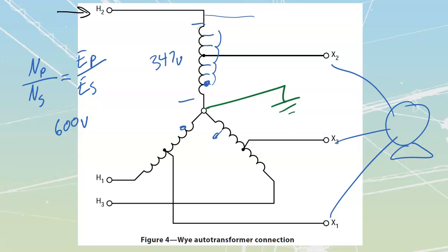Instead of having a waveform that looks like this, let me just draw one of these. That's what our waveform should look like. Our third harmonic voltage is going to cause it to lead higher, then it drops across the peak over there, and then drops faster, then leads higher at the bottom, drops and drops faster. It's really these lines that are tough on my equipment, as well as the fact that up at the top over here we get a little wobble up and down, so we get a fast dump and then a rise again of our fluxes. It just causes issues in the long term.